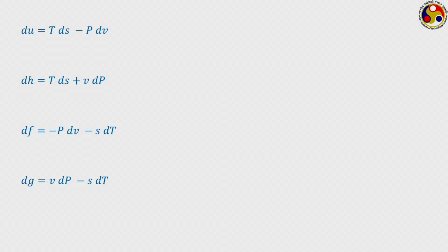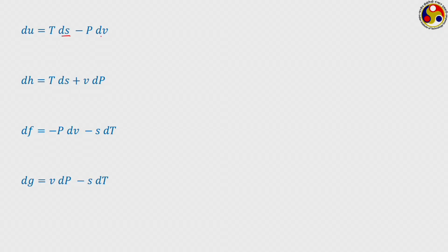Now, as internal energy is a property, then if this small s and small v are independent intensive properties, they are intensive, of course, they are written in intensive sense, and if they are independent of each other, then we can use the previous principle. So, I am rewriting that dz equal to m dx plus n dy, and if z has to be a property, we know that the principle is ∂M/∂y at x should be equal to ∂N/∂x at y.